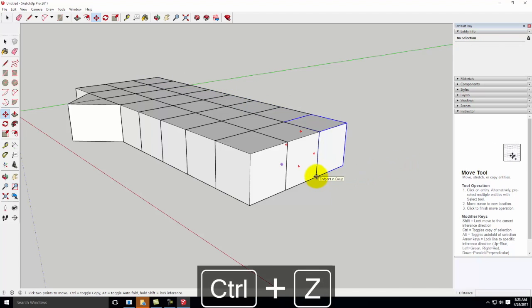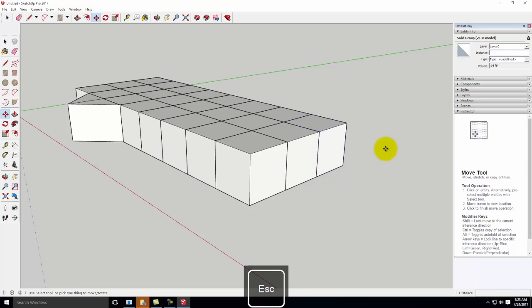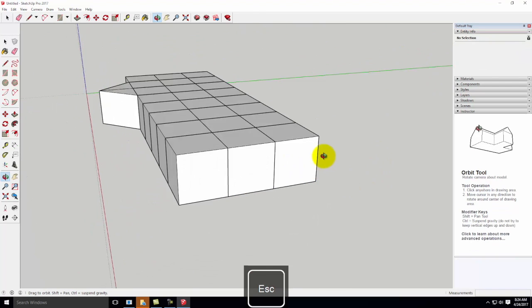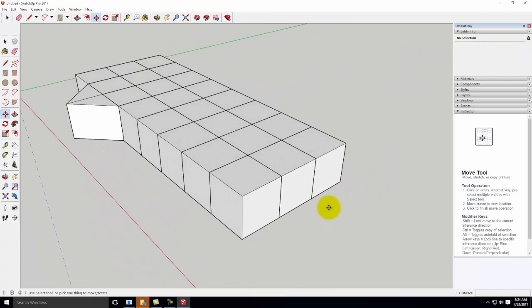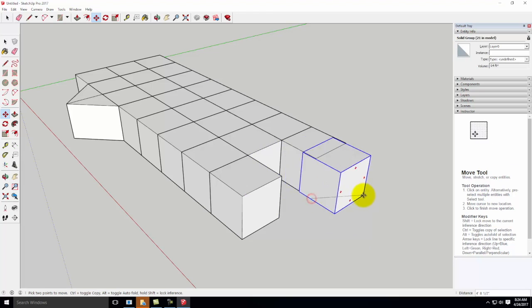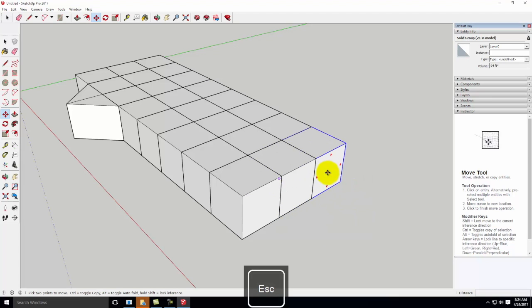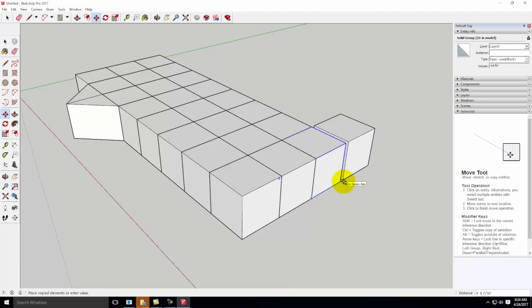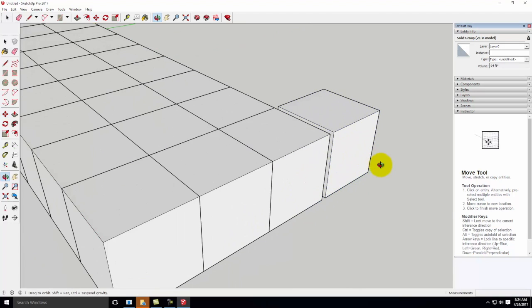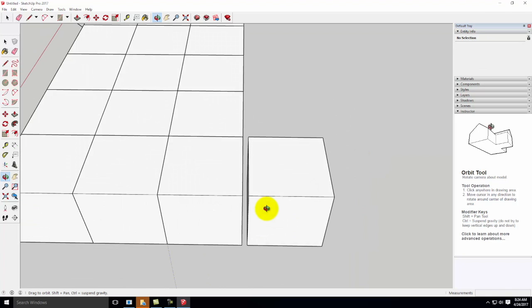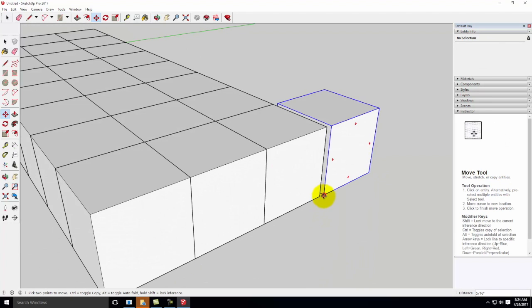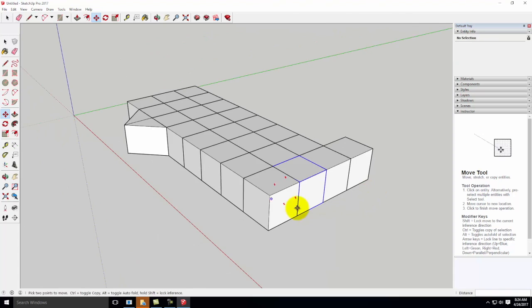You want to be very careful to make sure that you use your snaps when you do the copies so that your pieces line up perfectly. The other thing that happens is people aren't careful when they do a copy, and suddenly, let me copy it, two pieces end up close, but there's a little gap between them. That becomes a problem. So you really want to make sure that they're nice and tight. You're using those snaps to do it.